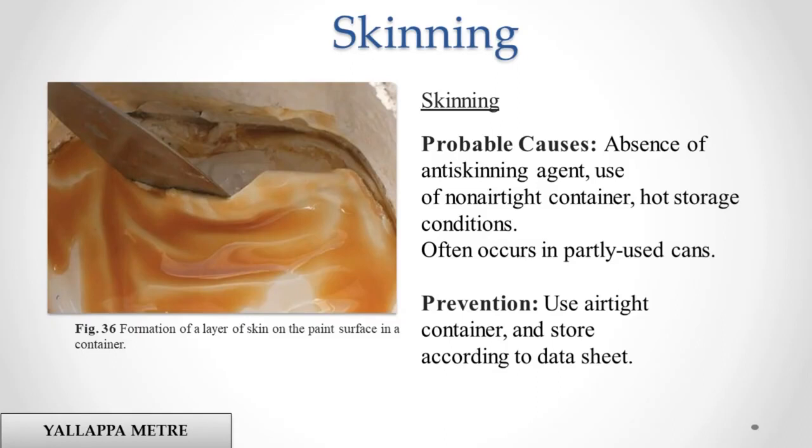Skinning. Probable causes: absence of anti-skinning agent, use of non-airtight container, hot storage conditions. Often occurs in partly used cans. Prevention: use airtight container, and store according to datasheet.